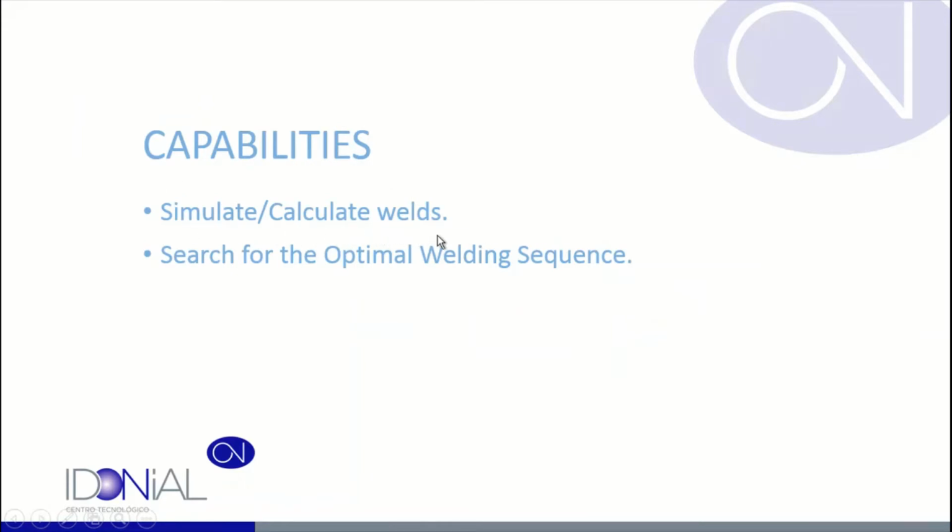The first one is to simulate or to calculate welds in which we already know the welding sequence. We know what we have to calculate. And the second one is to ask the system for help to search for the optimal welding sequence and also get the results of this optimal welding sequence in case we don't know it, which is most of the cases. This first part will focus on the calculation of these welds when we already know the welding sequence.